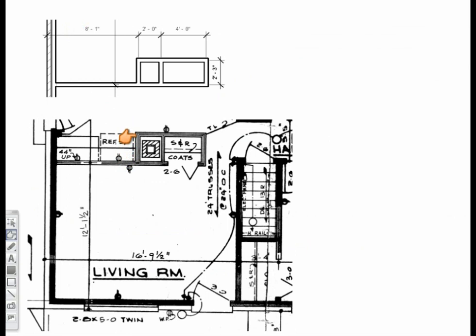Next, we will lay out the interior walls here in the floor plan. We will use the information provided in this diagram to locate the position of these walls. The first wall that we're going to put in is going to be this horizontal wall here that is 2 feet 3 inches from this wall.